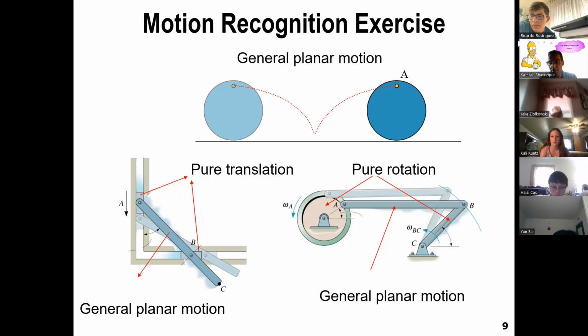How about the body of the bicycle? Imagine you ride your bike on a road, kind of straight. The body of the bicycle does not rotate, it just goes straight, like the seat, right? What has general motion, in addition to wheels, tires, and the sprocket? The pedals, right? When you use your pedals, they rotate technically about the center of the sprocket, but the whole bike is also moving, so it has general motion.